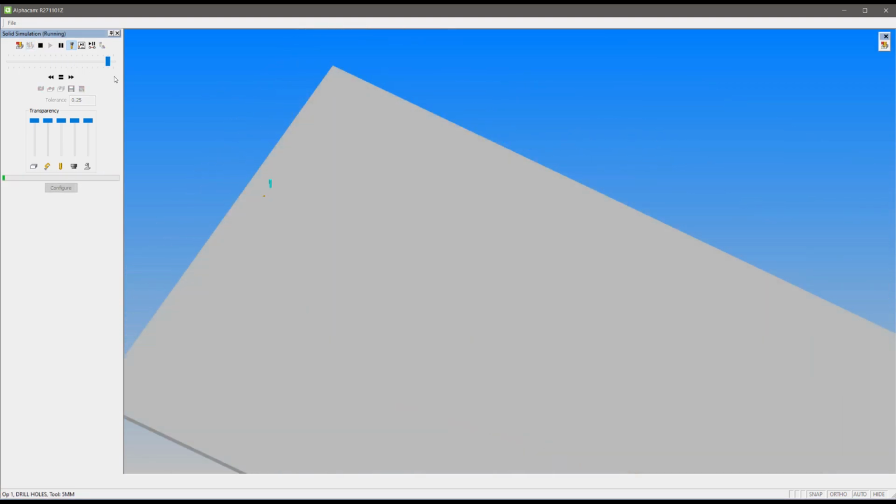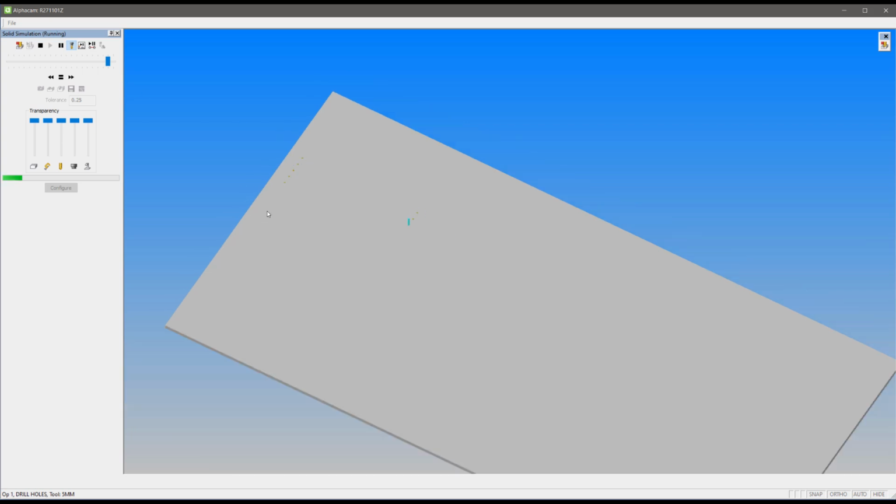Once the A program is finished, we'll take our sheet, we'll flip it over so that the two sides that were trimmed now sit against the pins. And then we'll run what's called the Z program. This file will then do the remaining operations and cut the parts out, and our parts will be completed.